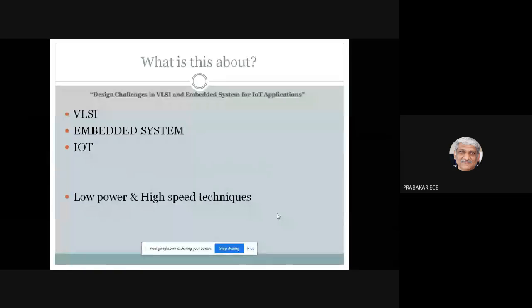The main thing is the hardware architecture is almost fixed. And the voltage to be given is again 5 volts or something like that, which cannot be changed. So how can I reduce the power consumption of a processor? The only possible case is I can reduce the frequency, the operating frequency of the basic clock, so that I can reduce some power. Supposing if the process is too slow, I need not operate at a higher frequency. So I give a reduced frequency to the processor and it has to work, so that a small power consumption is possible.